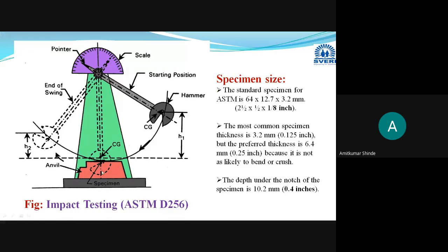Here you have to take care that you don't get confused between the two impact tests. The Charpy impact test is there, and the IZOD impact test is also there. But for almost all plastic materials, we go for the IZOD impact test.